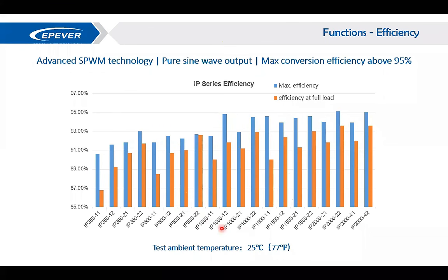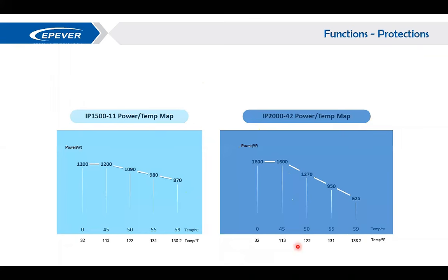Of course, this is the efficiency reported at a temperature of 20 to 25 degrees centigrade, and at different temperatures you will expect different values for efficiency because it changes when the temperature changes. And temperature always plays an important role for off-grid systems. Inverters, like all other semiconductor-based equipment, are sensitive to heat, and in general, they operate best at cooler temperatures.